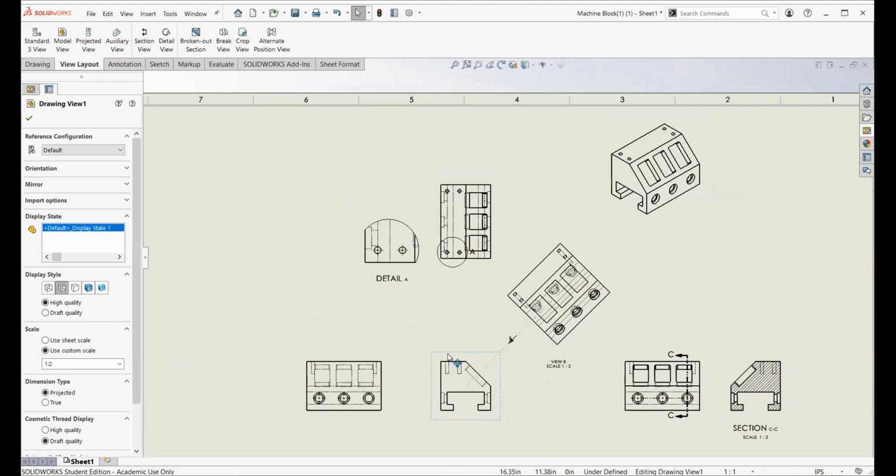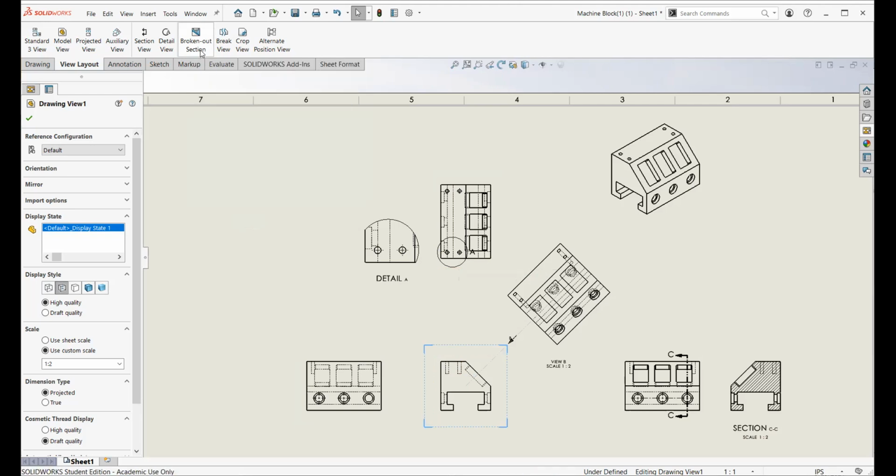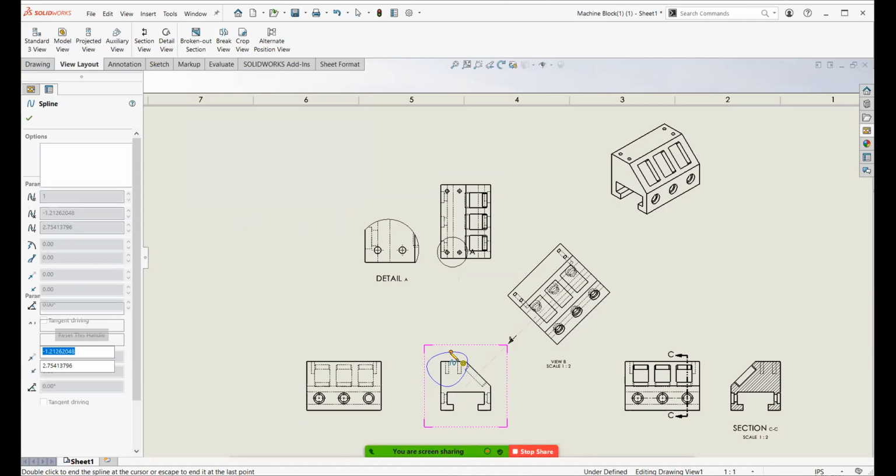So you know these two holes are not immediately in the surface. They have some depth. And we want to show the operator that he has two holes over here. So you can select the breakout view. You can just draw around that view here and close it.